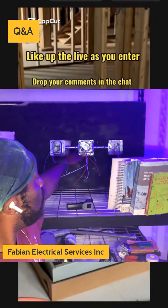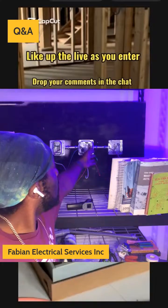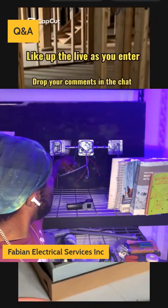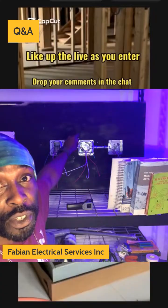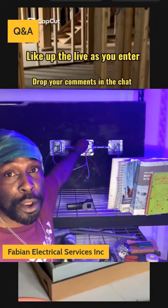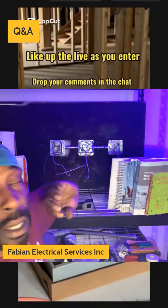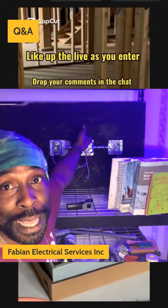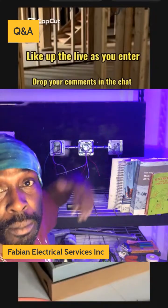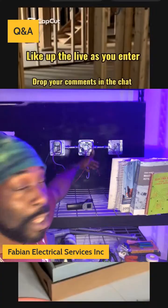So to reduce the deduction of the wire count, I simply place my ground wire onto the actual ground screw instead of making connections here. Instead of joining these two with a cap, I avoid that and I have some wires that I can play with in case I needed to pull more wire into here.